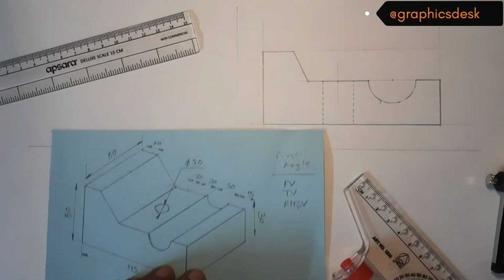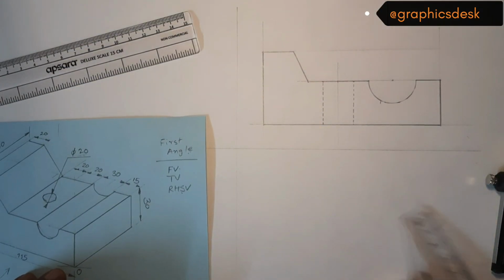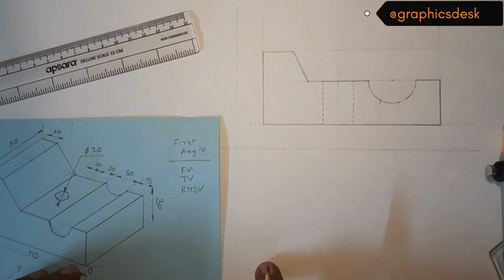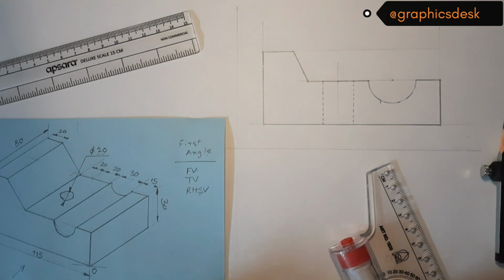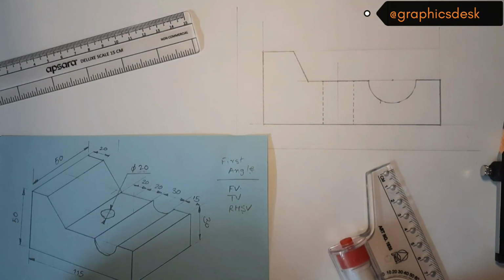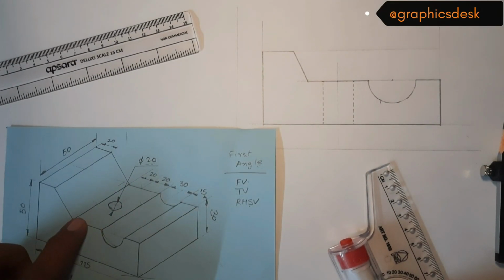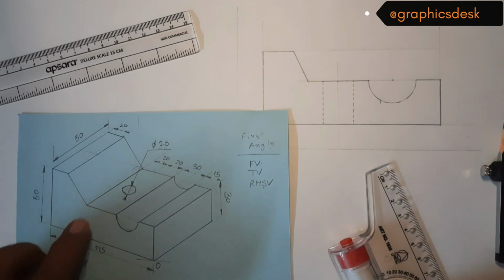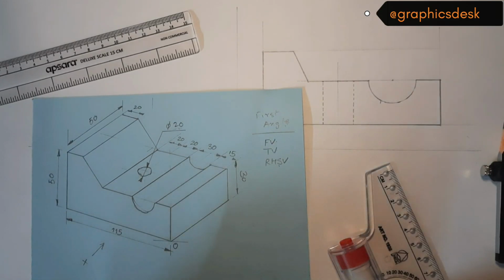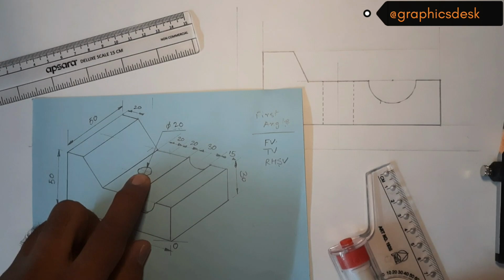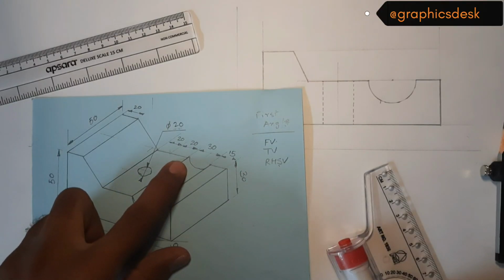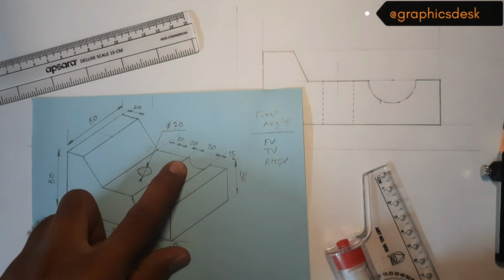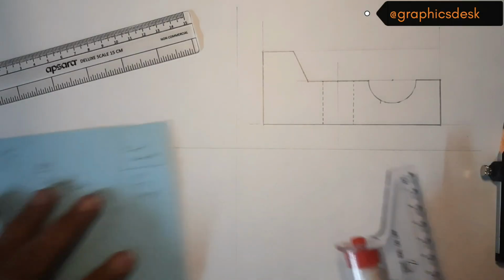Now, for us to draw the top view, which will be here, we have to carry the projections of this object over here. So let me carry these vertical projections here, and then we'll measure on these whatever the dimensions of this diagram that we have. Now, the top view would be very simple because it is a simple rectangle, just the hole in it, and all the lines which will be vertical lines in the top view are anyway coming from the projections. So let's draw the top view.